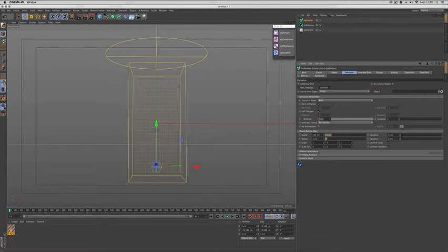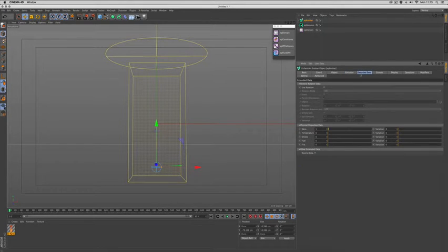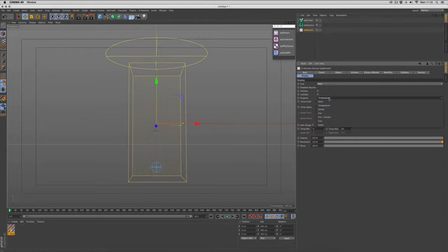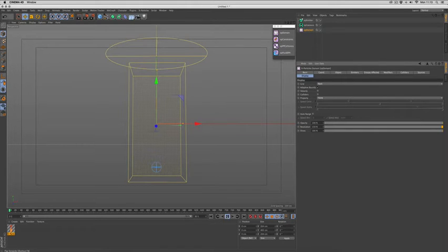Our emissions slightly higher. The way the emitter works is it has a tab called extended data, and inside here you have options for adding your temperature and smoke. So again, if we want temperature, we add it in. I don't want to see the temperature display on the domain anymore because I want to look at my particles. Push play, and you see you now have particles getting that information and doing the simulation.